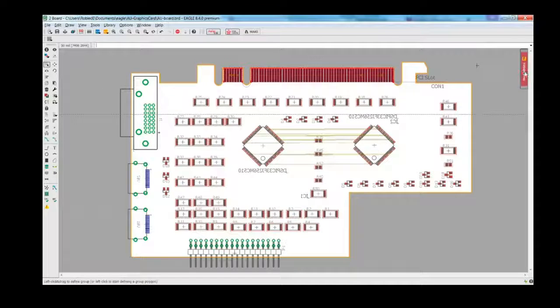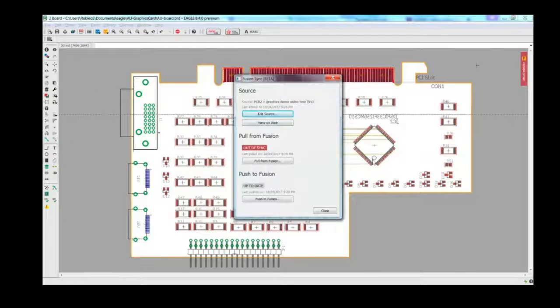So Eagle, by default, has approximately 300 libraries of components. They're categorized by manufacturers, or by functionality. So you have your MOSFETs, transistors, caps, the discrete components, your linear components. But we also have libraries by different companies like Infineon and Samtec as well. So yes, we have quite a bit. Now, Eagle does have a system by which in the background, we're constantly adding to the library. It's called Managed Library, so those libraries are constantly being updated as well.